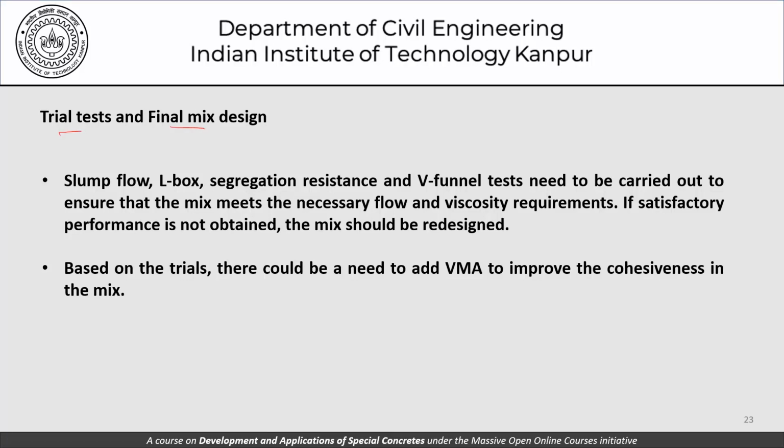be based on the slump flow, L-box, segregation resistance. V-funnel tests need to be carried out to ensure that the mix meets the necessary flow and viscosity requirements. If satisfactory performance is not obtained, the mix of course should be redesigned. And based on these trials, there could be a need to add VMA to improve the cohesiveness of the mix.